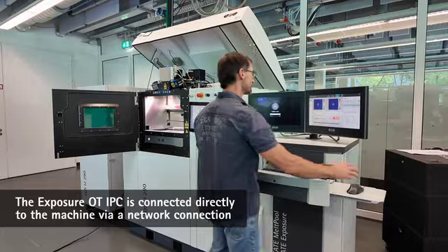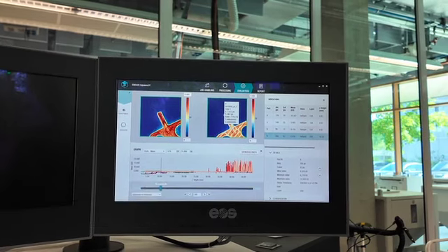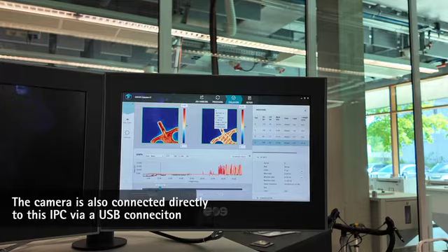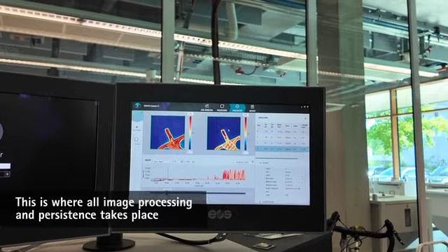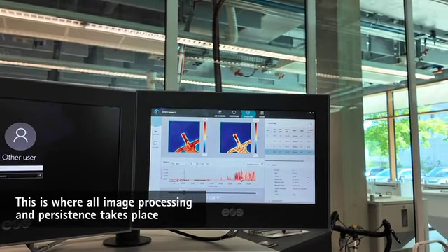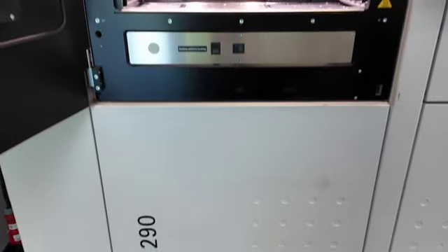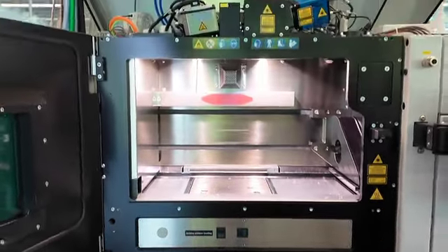So after each layer we end up with an image which can be interpreted as a heat or energy map for the process. All these four different signals rise with more energy in the process, whereas spatters, welding plume and melt pool are most important if we want to evaluate the process stability. The last one, resolidified material, is very useful to evaluate the overall heat management of the build process.